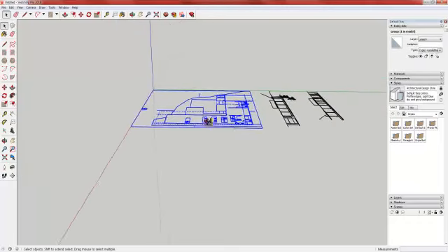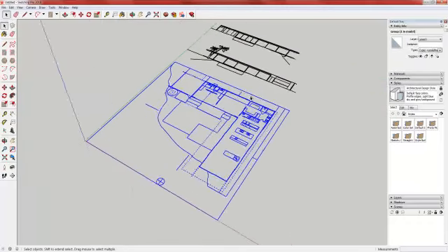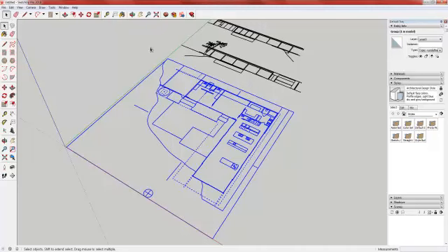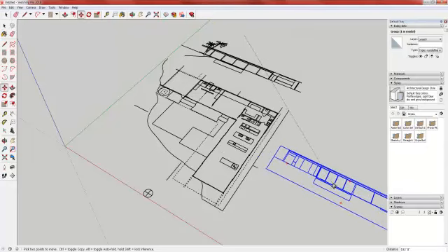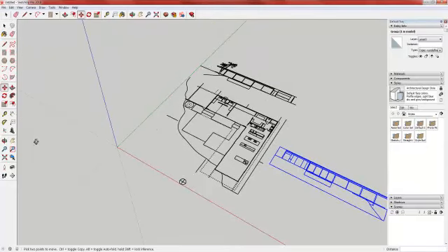So the nice thing about that now is that I can separate the sections from the floor plan and move the geometry wherever I need to. I know that this section comes right through the building. It's actually coming through right in this area right here. So I'm going to take this section, which is cut through here. We can see the downward slope that happens on the front edge of the deck. And I'm going to move that section in a little closer to where it belongs.